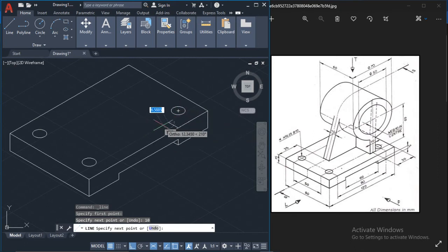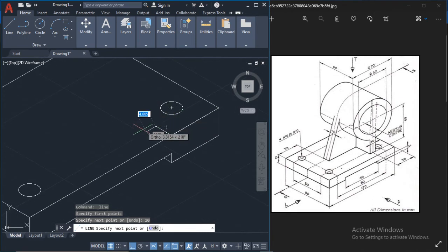That's the center. So now, because that's the center, I can just do this. I can bring this across by 5, because it said that the width of this part here is 10. This is the center, so I can do 5 in this direction, and then 5 in the next direction. So that's 5 as well. Yeah, so we can delete this line and delete this line that we used as construction. So we just need this line right here.